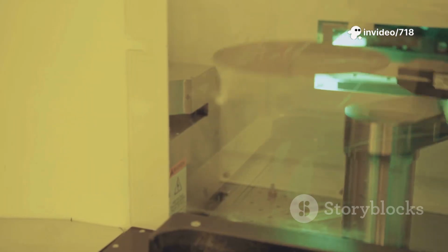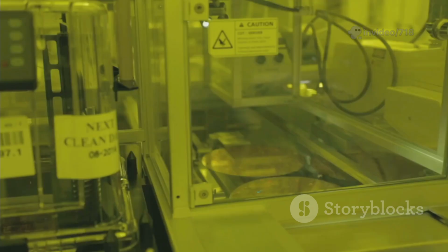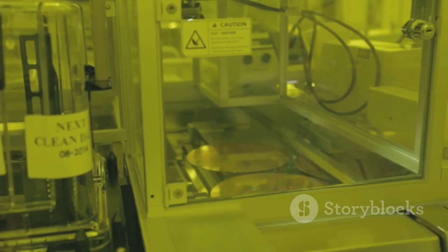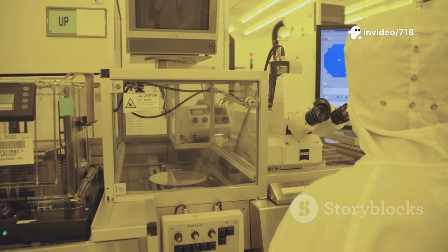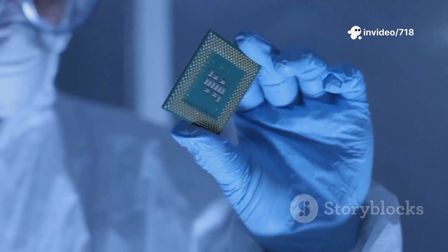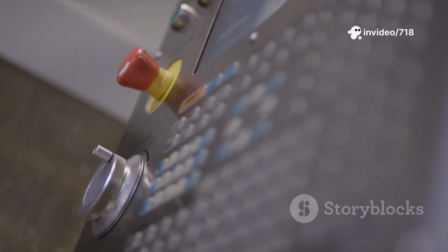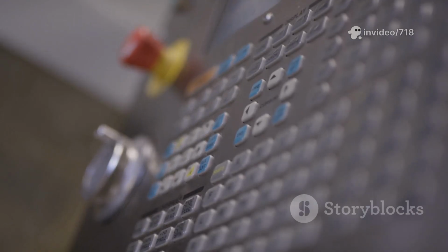possible. Once all the layers are built and the fabrication is complete, the wafer, now containing hundreds of individual DRAM chips, called dies, is tested. Probes make contact with each die to check for defects. The dies that pass the test are then cut from the wafer using a high-precision diamond saw.